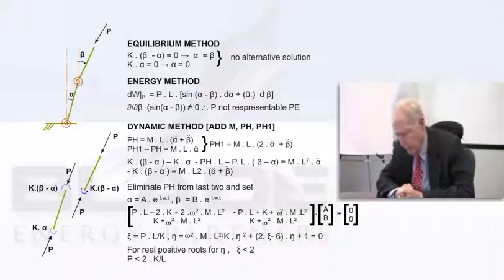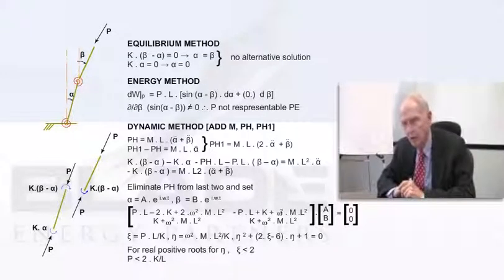If you put on the follower load and struggle, as Timoshenko shows you how to struggle in his book, he gets a number that's 2.03 times larger than the vertical load. So the follower load also, in this case, is larger by a factor of 2. In our problem, it was larger by about a factor of 4.